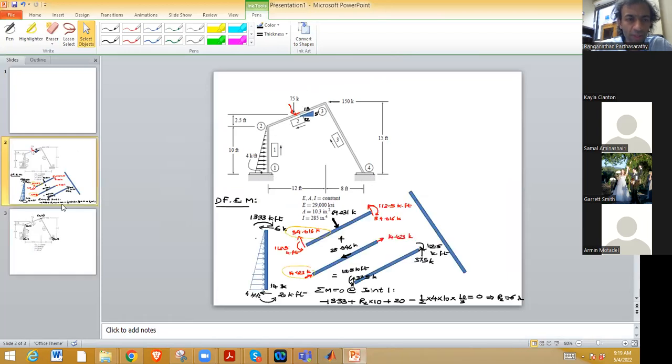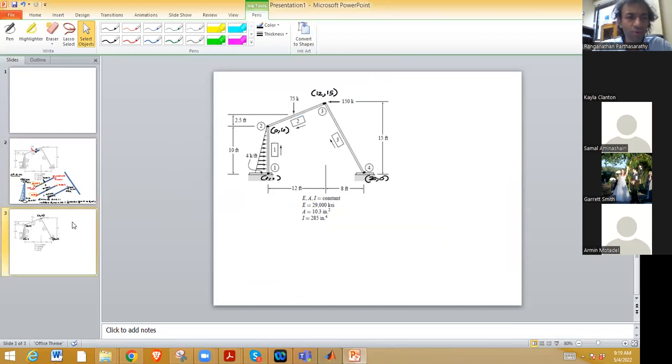So next is we have to make the vector of fixed end moments. So if you remember this equation, K U plus the fixed end moments, this is what is equal to the total applied forces. So this is true for each member, also for the total frame as a whole. Okay, so